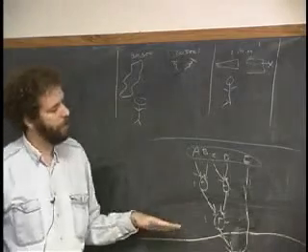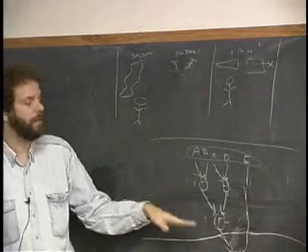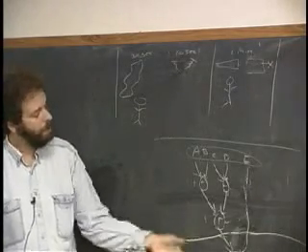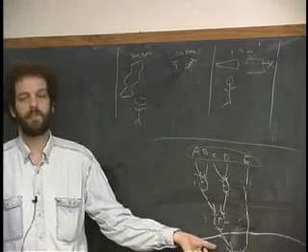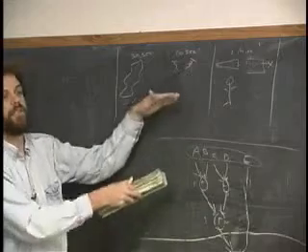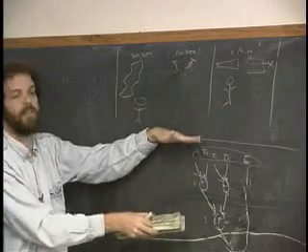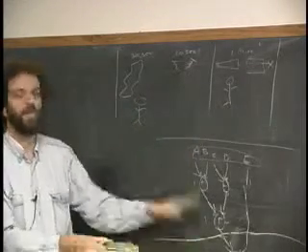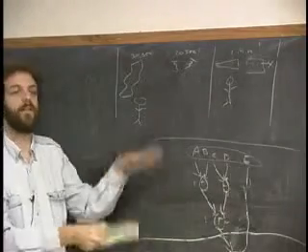In the same way, if we don't want to use an excessive number of registers to form a pipeline here, we look for the element that takes the longest time, surround it with registers, and then chunk the rest of it so that the propagation between chunks is that number or less, but as large as possible.